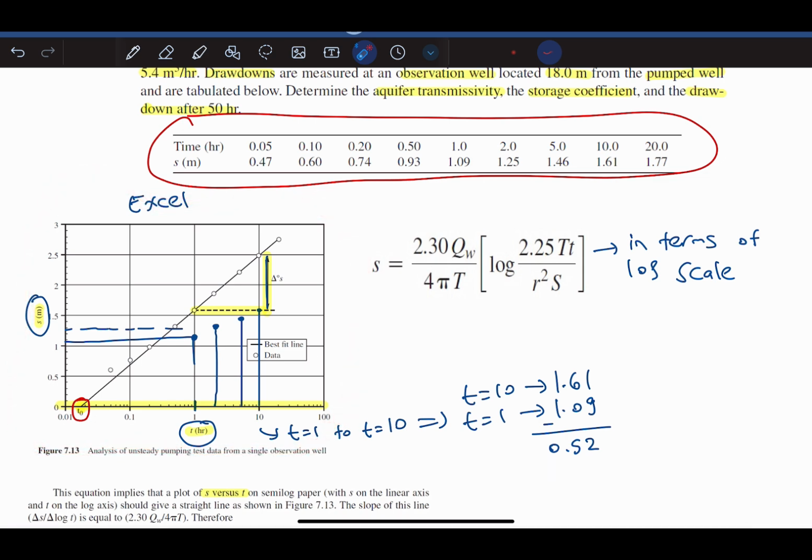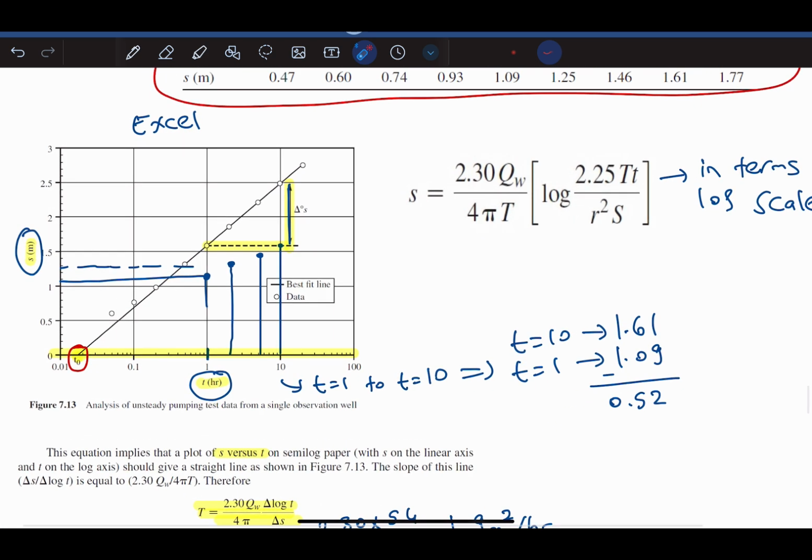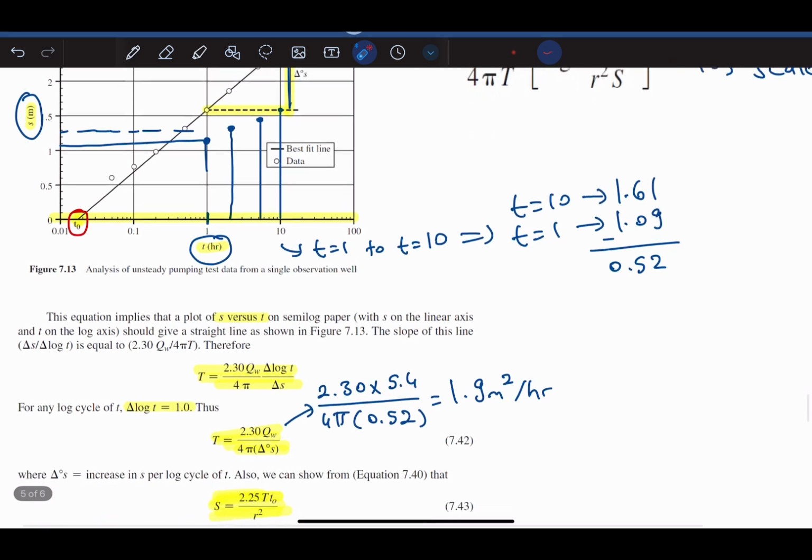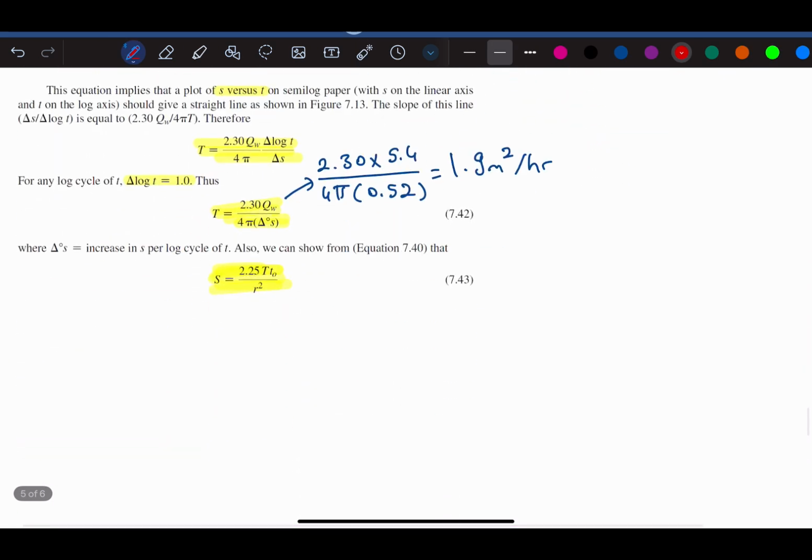And in this graph also, you can find this T0. As I mentioned, you first need to draw a best fit line for all of these points. And when this best fit line intersects with this horizontal line, this is where we have T0. So after calculations, you will get T0 as 0.0082.